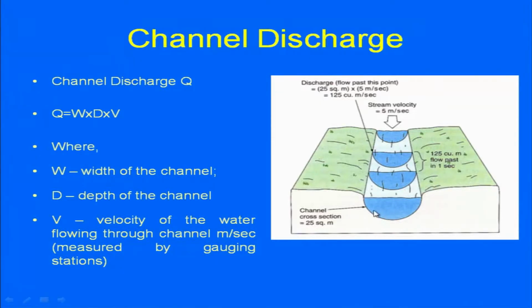When the cross sectional area was large, that amount of water easily flowed through the channel. But if the area has been reduced and the rainfall remains constant, you have less area available to siphon out that amount of water through the channel, and it will spill over, resulting in inundation, getting into the flooding state and inundating the nearby low lying areas.